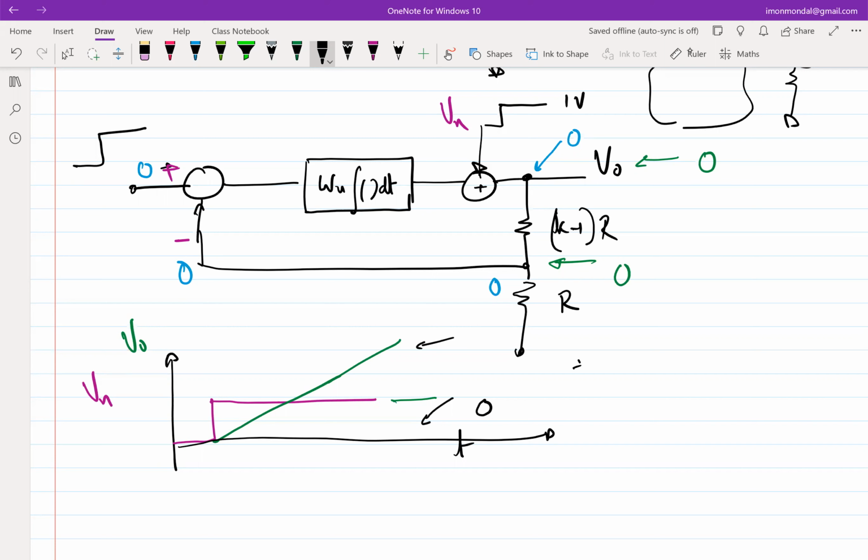The whole purpose of putting in negative feedback is to ensure that the input of the integrator doesn't go to some finite DC value, which means the loop will keep on correcting all the time. How it will correct, we'll see, but it will keep on correcting.